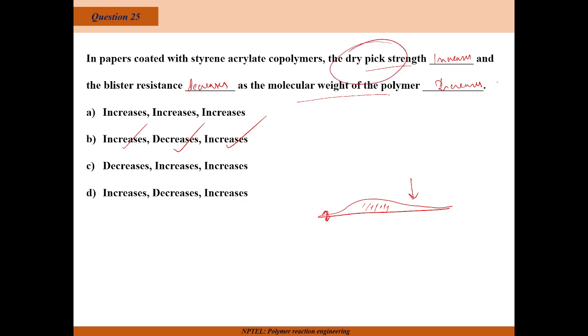During the process there will be wet peel, I think, and after the completion of the process it will be dry. I am also not particularly sure about that. But basically, dry peel is the structural strength of the attachment between, say, the paint and the surface. And when that is high enough, we can avoid the blister. So basically, I can say this is the reason why we cannot use varnish and other kinds of paints on metals.